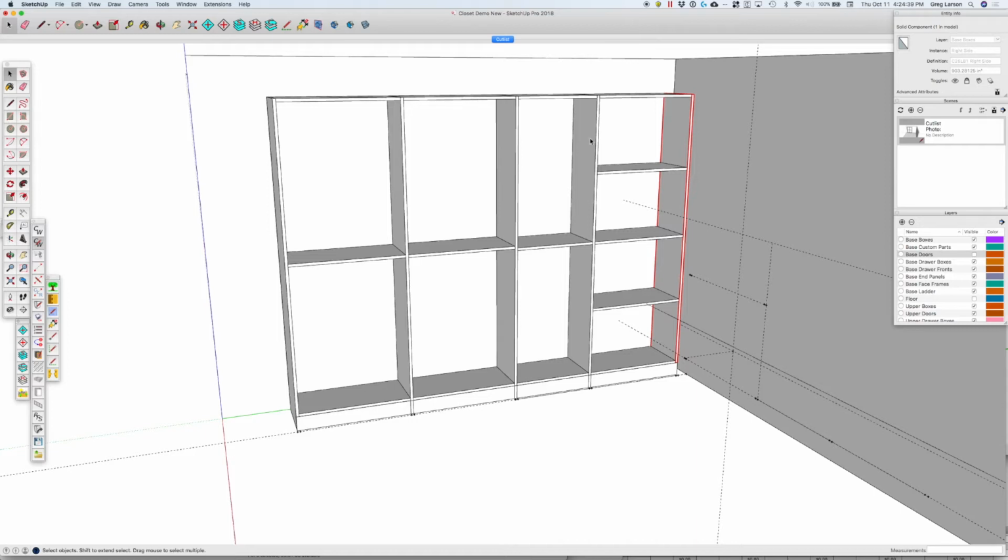If we want shelf pin holes on this side, and let's say this is going to be a CNC job, we're going to have some weird boring pattern on this side for our angled shelves, but on this side we want standard line boring. Unless we can CNC on both sides of a part, that's going to be difficult. So we might have to manually drill one side of it and maybe automatically drill the other side.